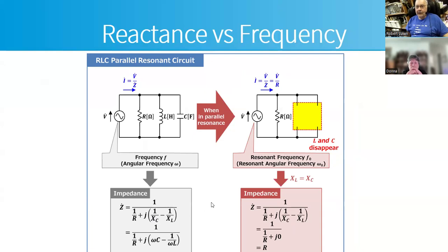We'll talk about how we calculate parallel resistors, capacitors, and inductors in a bit, which is how you calculate parallel impedances. When we have resonance in a parallel circuit, again, the L and C are going to cancel out, and you're going to be left with the R value.